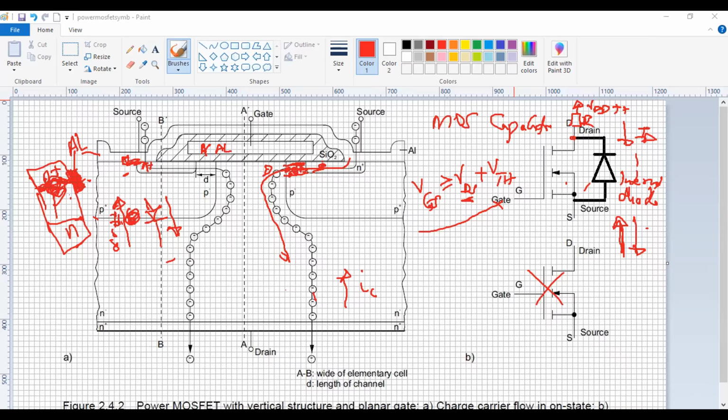Yes, there is something I would like to know, Dr. You talked of the purpose of the aluminum metal: to get rid of the inbuilt NPN BJT. Then, if we get rid of the inbuilt NPN BJT, it means we are now creating the PN diode.